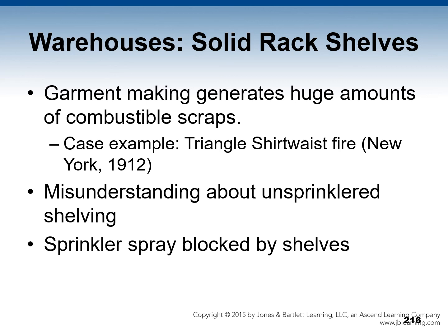So in solid rack shelving, in garment manufacturing, one of the outcomes was that the width of garment cutting tables is permitted to be 48 inches. Some jurisdictions have erroneously interpreted the 48-inch concept to permit several levels of unsprinklered shelving no more than 48 inches wide, which is of course incorrect. Racks in retail big box stores have shelves that block sprinkler spray. Something to look at next time you go shopping.